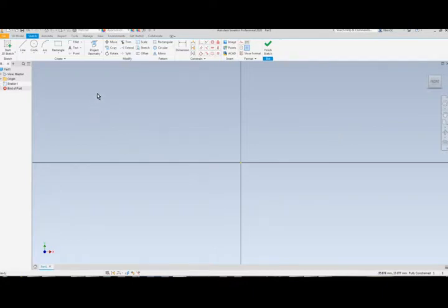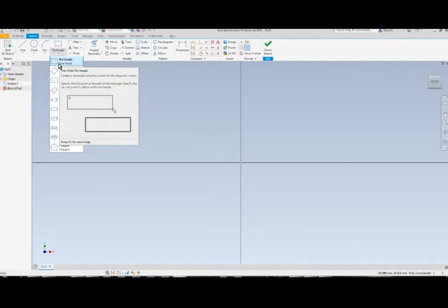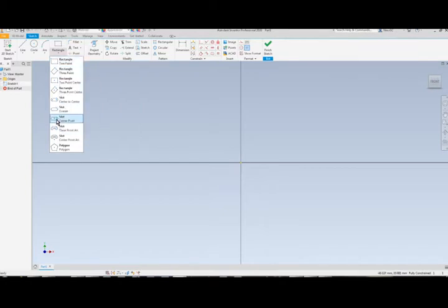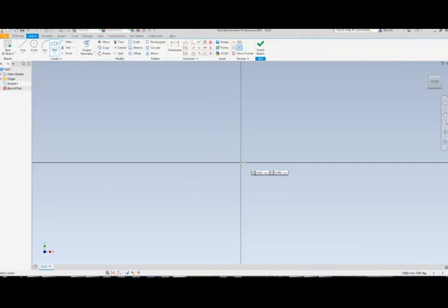Our first step is to create our sketch, and for our first sketch I'm going to use something a little bit more interesting than just a simple rectangle. I'll use a center slot. I'm going to start the center slot at the absolute 0, drag out, and give it a half-sized dimension. So I want this to be a total of 70 millimeters in length from center to center of the slot. So I will give it a 35 millimeter to indicate the halfway point.